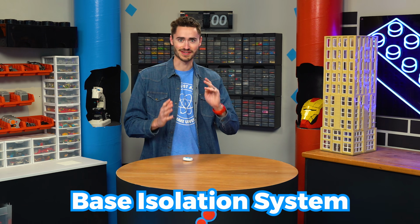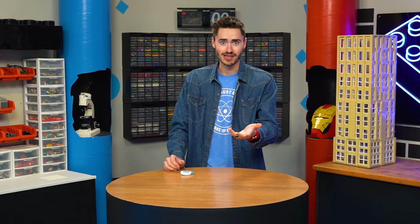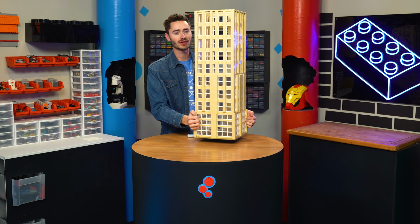And for this one, I'm gonna use a technique called a base isolation system. Essentially how this works is the building is placed on flexible bearings or isolators, usually made up of layers of rubber and steel. And these actually absorb the seismic energy waves that go through the building, effectively disconnecting the building from the ground and reducing shaking by up to 90%, which is crazy good. So we're gonna take this and put it on some bearings to give it a little bit of wiggle room.